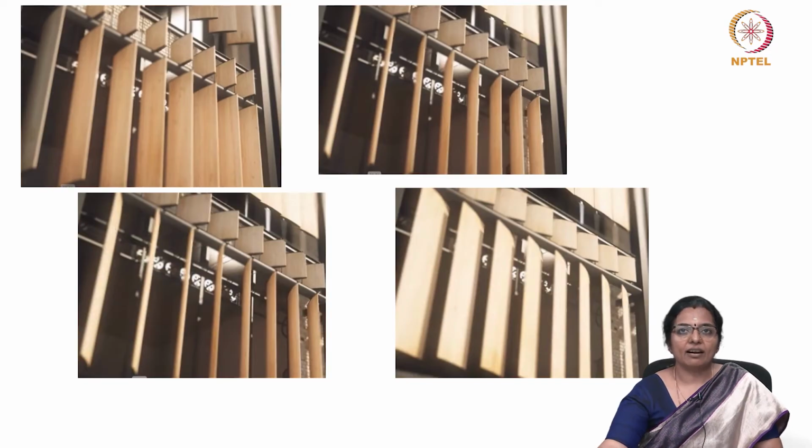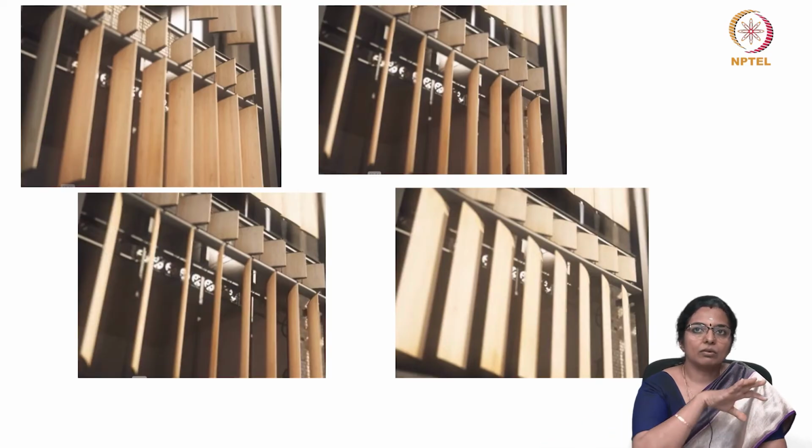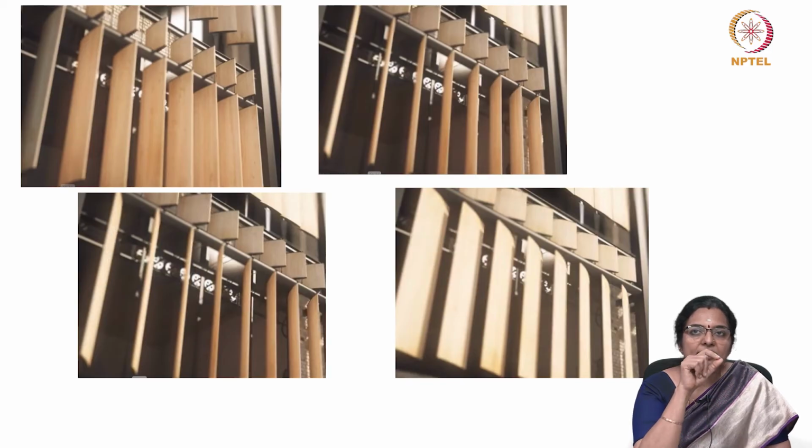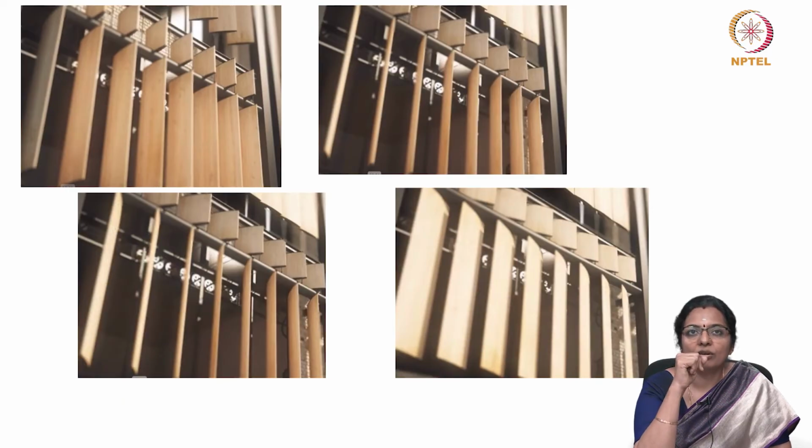We will look at yet another shading system, and this rotates in 3 directions according to the sun's position. Tyler Short has designed this, and it is called the Penumbra kinetic shading system. It uses traditional static components that make the louvers swing out to create the depth that is required to either prevent solar radiation or lighting from entering inside.